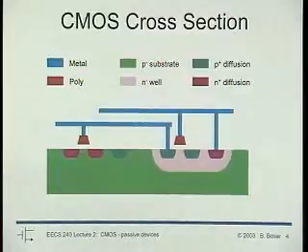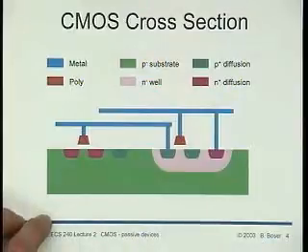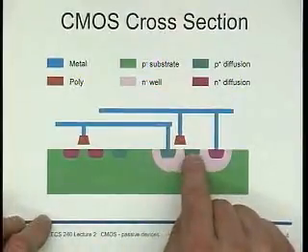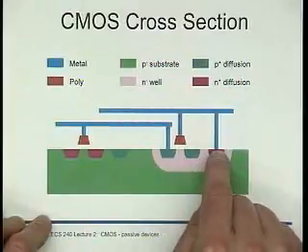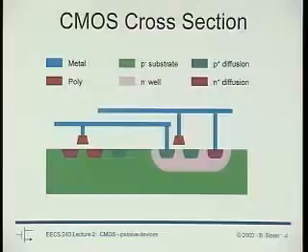Source, gate, drain, bulk, right? 4. How many terminals does this transistor have? Source, gate, drain, bulk, substrate. A terminal is missing in SPICE, huh? Realize? Well, why is that?